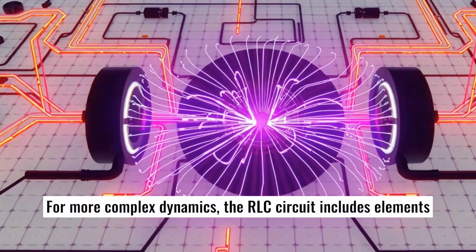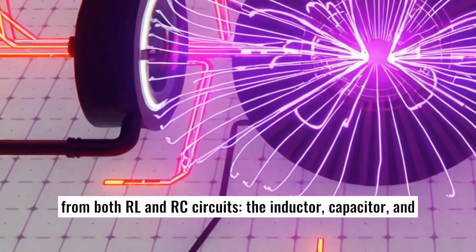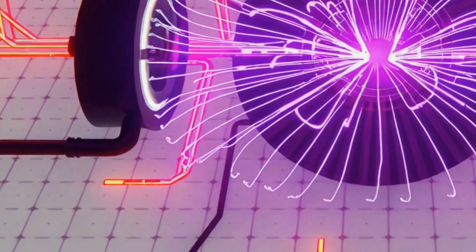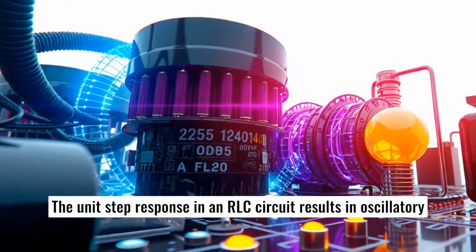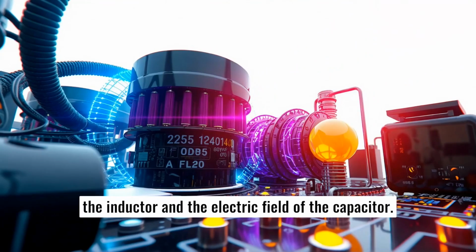For more complex dynamics, the RLC circuit includes elements from both RL and RC circuits: the inductor, capacitor, and resistor. The unit step response in an RLC circuit results in oscillatory behavior due to the energy transfer between the magnetic field of the inductor and the electric field of the capacitor.